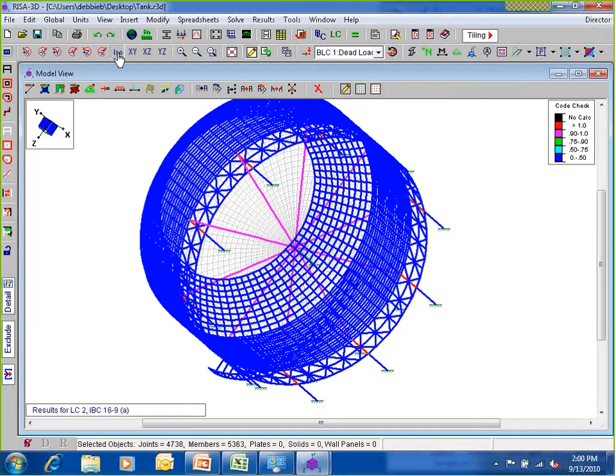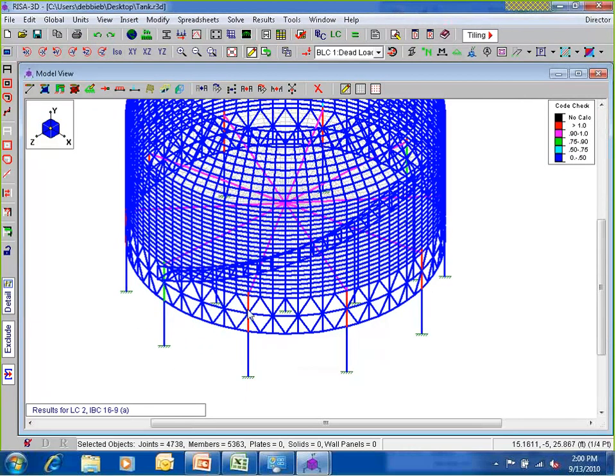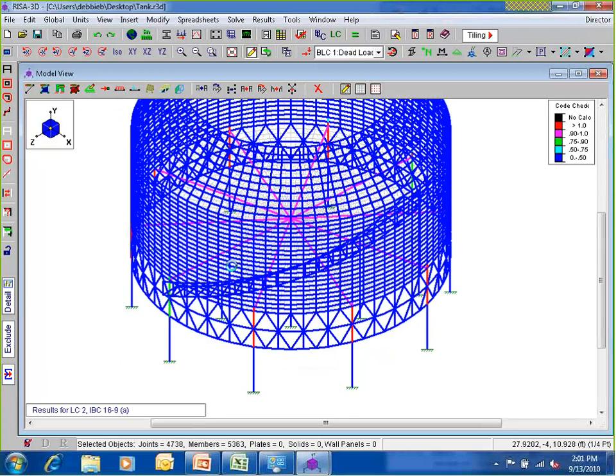What's failing, like we said when I was talking about this, is probably that failure mode directly from the tank to the vertical to that column. So an option here is to size up these webs, but that almost seems a little bit unnecessary. What I might suggest, although we don't really have time to do it today, is to create a different section set for verticals directly underneath these supporting beams. Those would be the ones that get sized up, not the rest of them, okay? That would probably be my step.